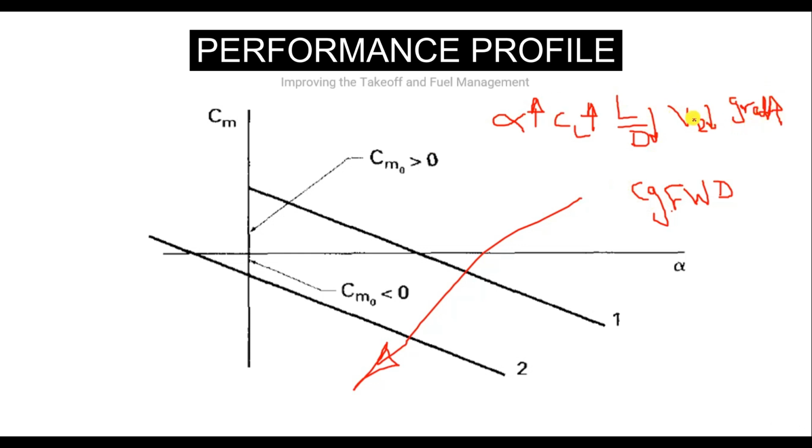You want better fuel consumption, move the CG aft, you get a higher angle of attack. Let me say here, CG aft, just to be able to continue and relate. CG aft, alternate to forward CG. Higher angle of attack, higher CL, which means I need less speeds.